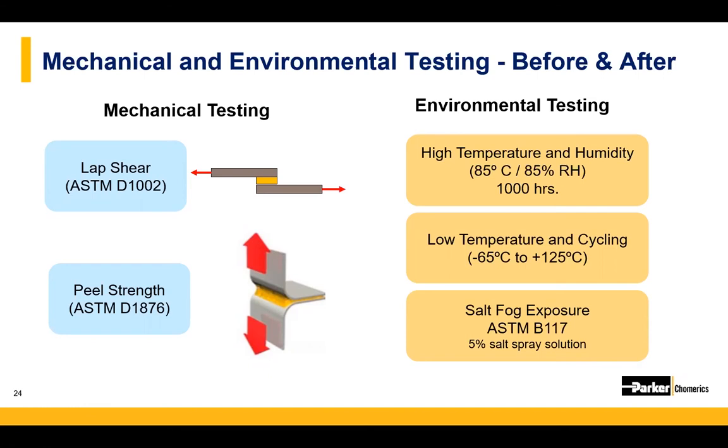Yeah, and as Ben alluded to, most of these materials are also tested on how they would hold up in harsh environments. So environmental testing can include high heat, high humidity testing, as well as salt fog testing to validate that the conductive compound will maintain its mechanical adhesive strength and its electrical properties. Obviously, we're trying to minimize galvanic corrosion when exposed to these environments without the additional protection.